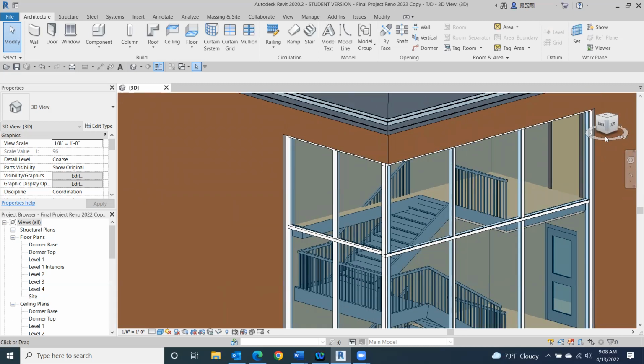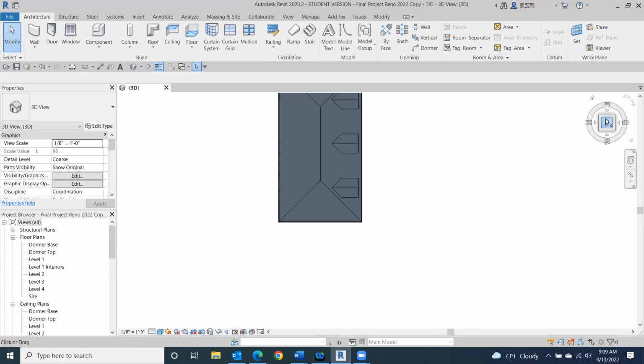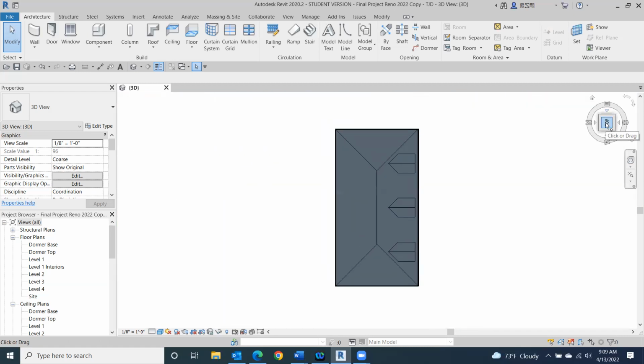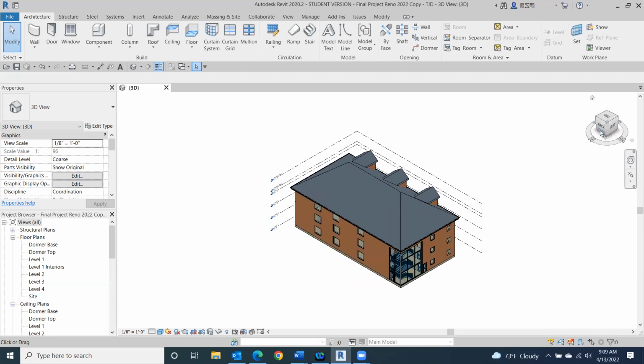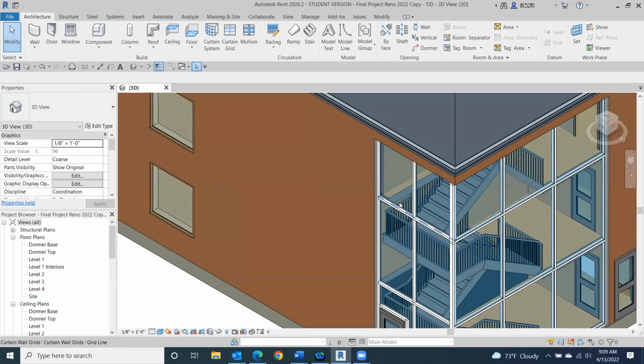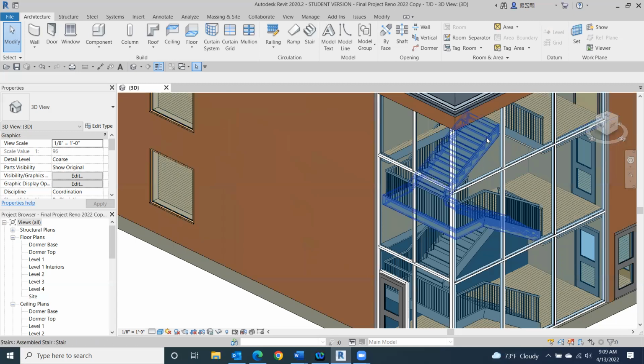A couple of things caught my eye right away. If you look at this third floor, this floor looks like it was actually cut at an angle. You always want to do a straight-on view when you're editing floors or walls or anything, because if you are at an angle, it will give you something that looks like this, where that floor is not completely finished.